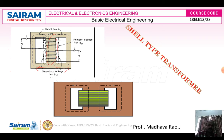It is suitable for low voltage applications, and similarly, to reduce the insulation cost, as in the core type transformer, here also near to the core we have to use the low voltage winding, and sandwiched between the low voltage winding we need to use the high voltage winding. So this is about the shell type transformer.